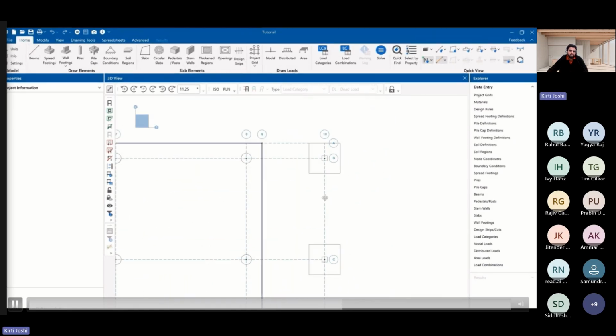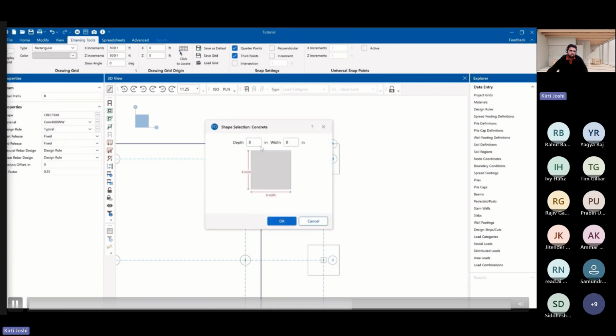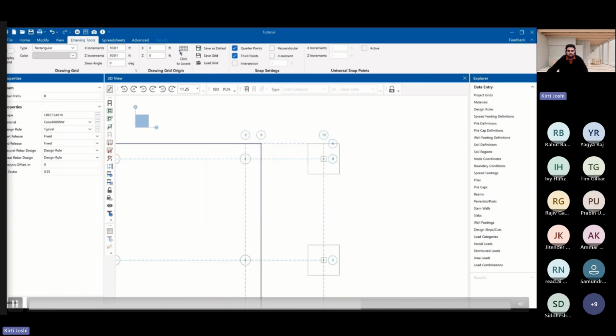Right now you can see I have zoomed in, and I want to connect the footings with the grade beams. You can select and give the sections, like the shape and the material property. Once you click on this, the property panel is active at the left, and you can assign all the properties there. You can connect between them, and it will create the grade beams. While you are using these options, you can continue as well. Like I created the 3 grade beams here.